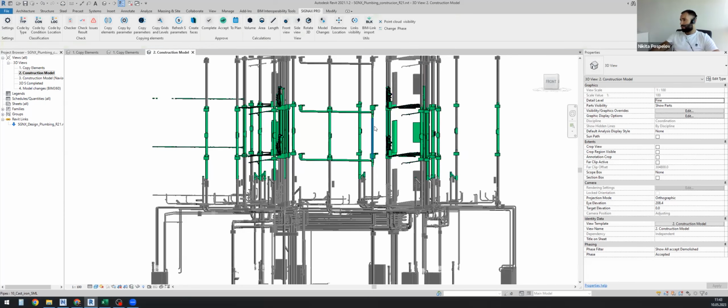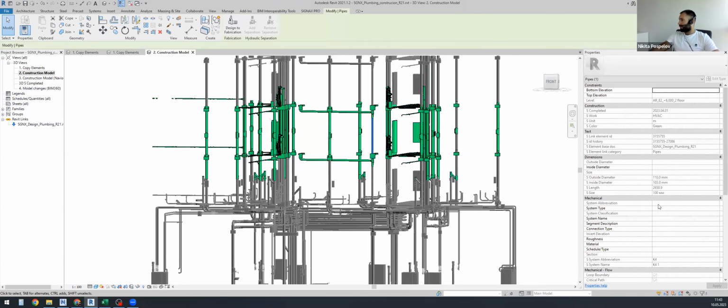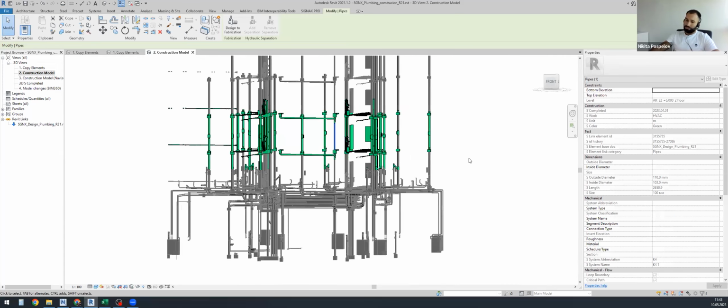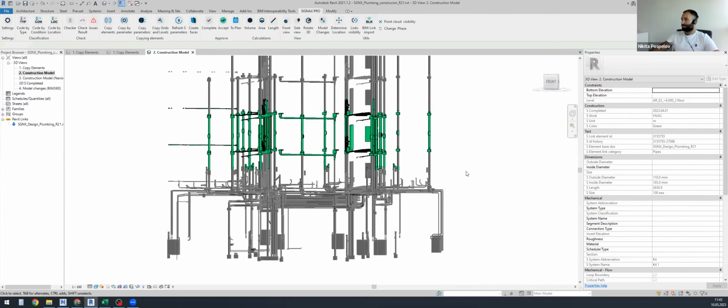Right now in Revit, I just created additional attributes for each element: completed date, work type, units, and the color. So you can also export this information to Navisworks and continue to work on scope calculation inside Navisworks.